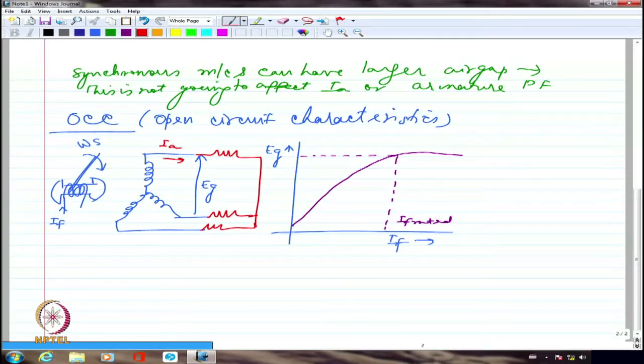That was also three-phase. So both of them were revolving magnetic fields created by virtue of three-phase currents being pumped in through three-phase space distributed winding. In this particular case, I have one revolving magnetic field because of a physically revolving magnet.